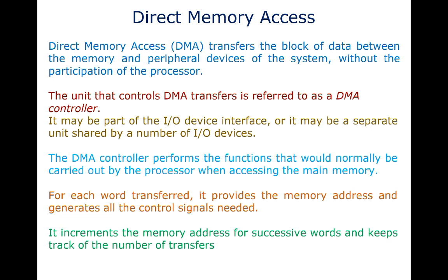In the previous video lecture we discussed the topic of instruction execution. From this we have an idea of how the processor executes an instruction. We saw the role of the PC, IR, instruction fetch, decoding and execution. From all these things, we understood that the processor communicates with the memory by using a system bus: the address, data, and control bus.